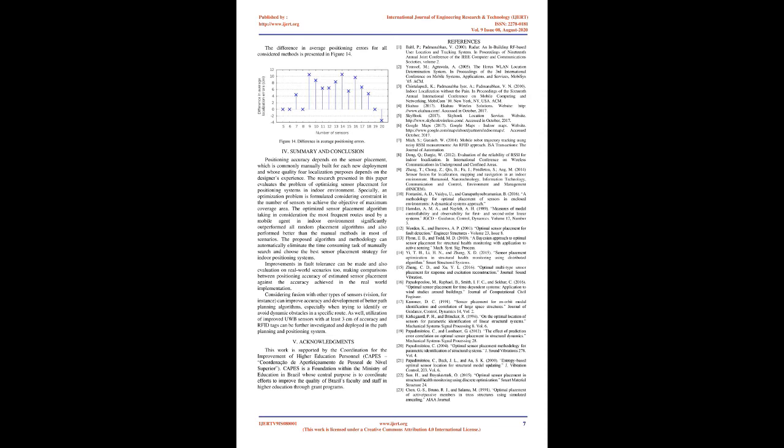To obtain a general overview of mobility patterns in the floor plan, the algorithm is simulated multiple times to generate a degree of importance over a specific path. The importance over a specific path is represented by an increased probability in a specific cell grid. The path planning algorithm will then use that data as a way to choose the most appropriate path the next time it runs.